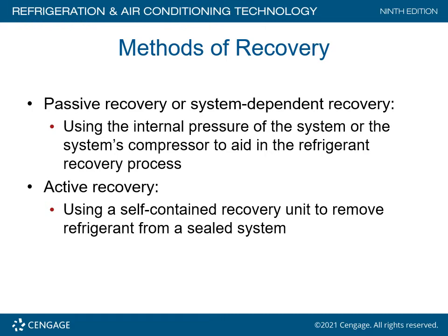Active recovery. This is the type of recovery you will be involved with continuously on air conditioning and refrigeration systems. It utilizes a self-contained recovery unit to remove refrigerant from a sealed system.